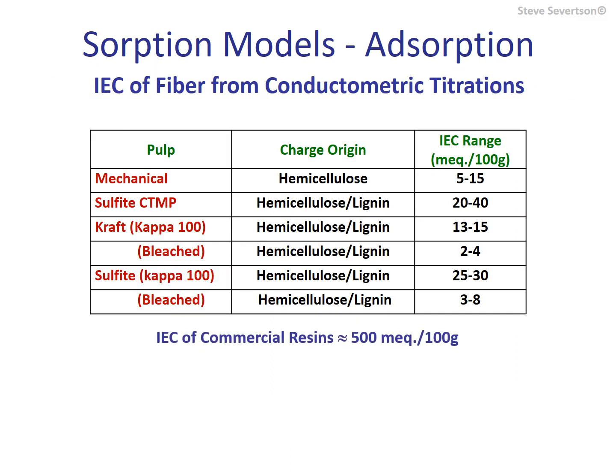Wood fiber processed for papermaking possesses a low ion exchange capacity relative to commercial ion exchange materials, but the values are significant enough that the fibers carry a relatively large ion load. Furthermore, molecular and polymeric additives used to aid in production or impart certain properties into commercial paper products are typically cationic, allowing them to exploit the ion exchange sites of fiber surfaces.